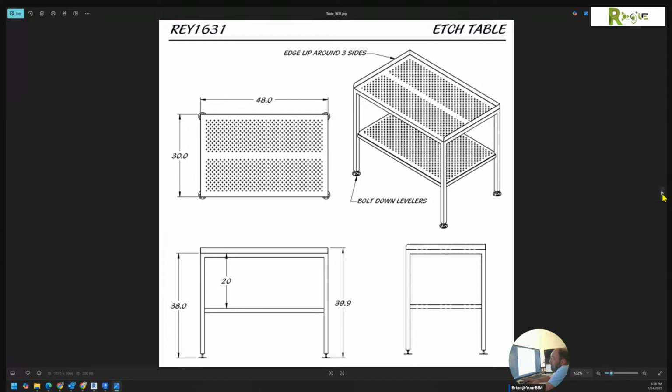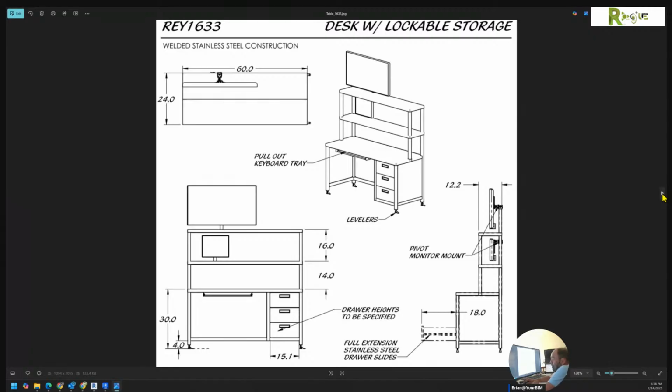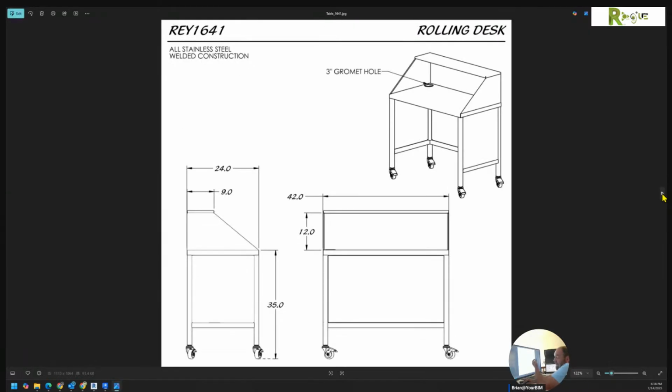And that was the route I went first, and it ended terribly for me. Okay? Because that structural, the tube steel and things like that, which is actually what this was made from, was where my initial idea was. But you'll find that those structural families aren't real strong inside of other families, and some of the functionality is lost as well. So I had to create all new types of structural. And I'm going to show you the benefit.